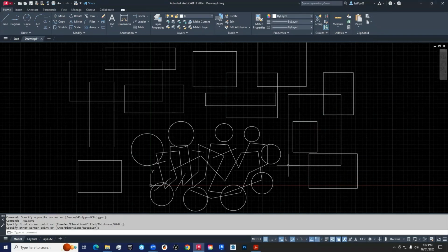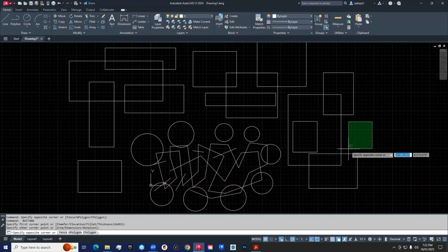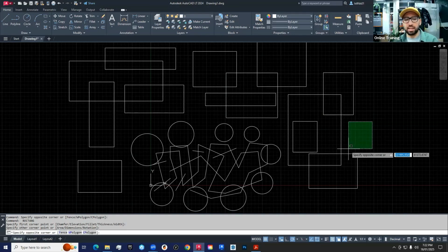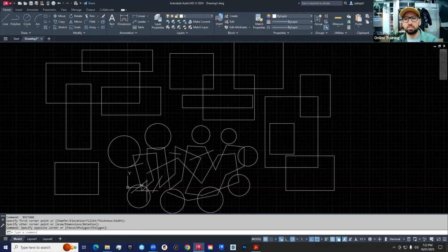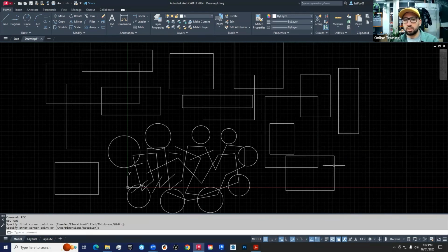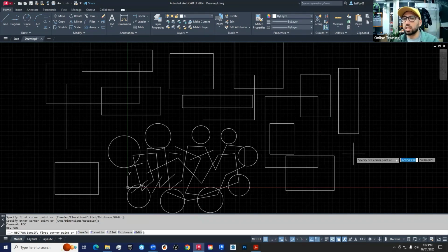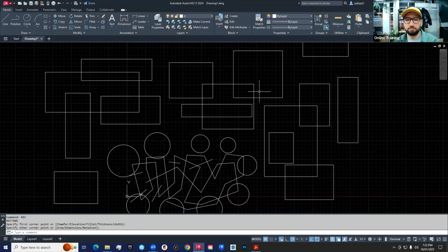So when it's highlighted green, what does that mean? That's the selection. That's not an object. I'm gonna explain it exactly in 5 minutes. That's selecting objects. This is not a rectangle, actually. If you have a look right there at the bottom, it's asking you to specify opposite corners. It's not a rectangle. To make sure you are in a rectangle command, this one should say rectangle at the bottom left right here in the command line. If it's not, then you're probably not in the command. You just need to type in REC. That's the rectangle. If not, then you're just probably making a window selection.